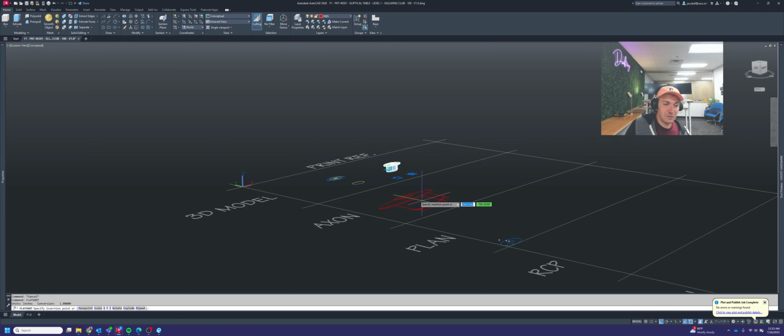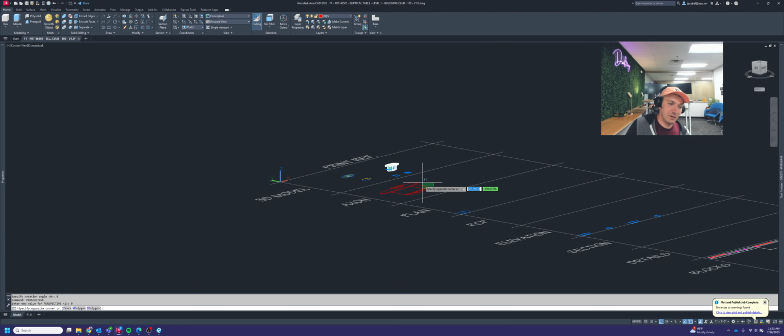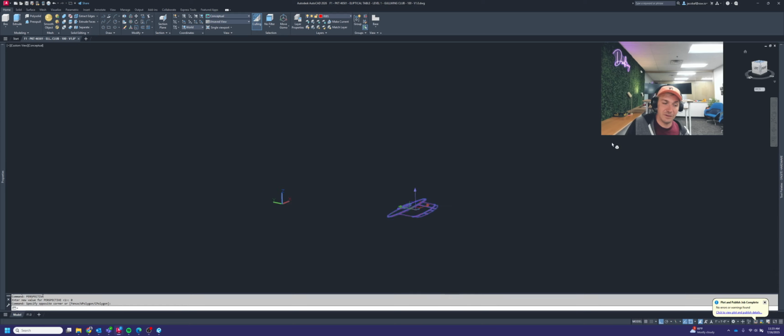But what I'm going to do is drop this up here, set my X scale factor to 1, my Y scale factor to 1, and my rotation angle to 0. Then before I finish out this thing, I'm going to go perspective again and type in 0 this time to turn it off. So we'll go back to a normal sort of view.